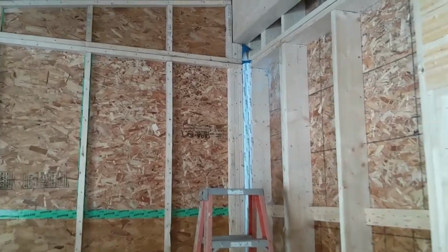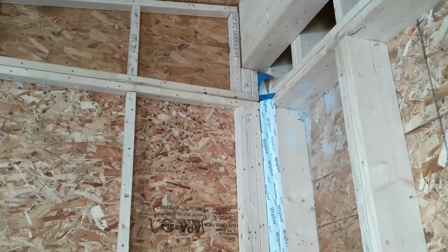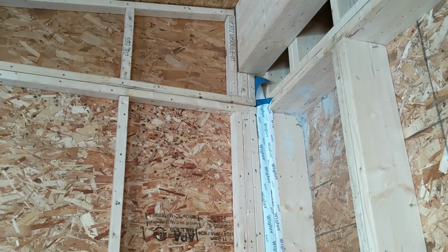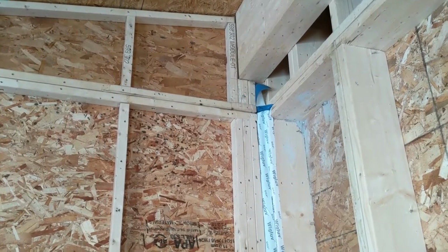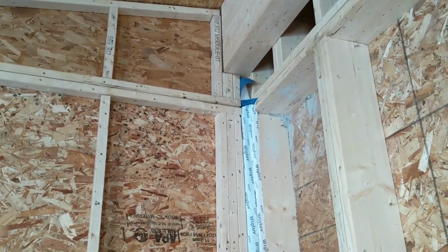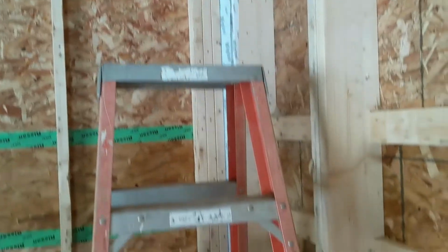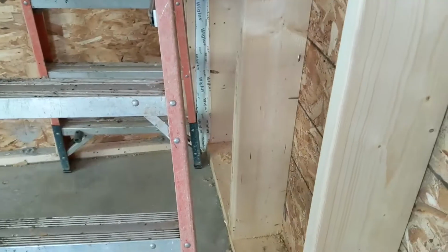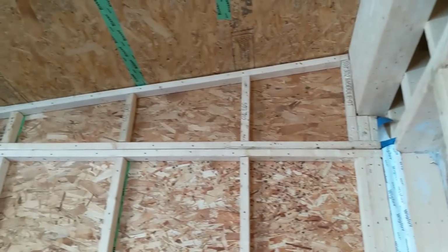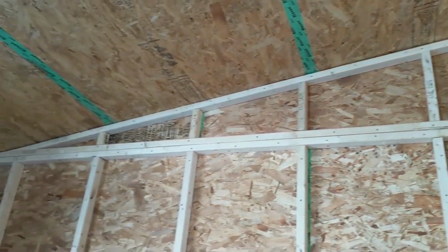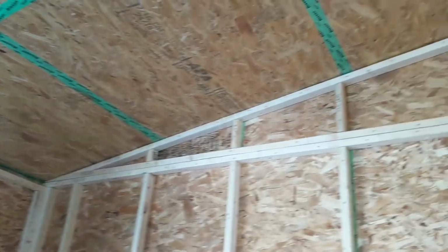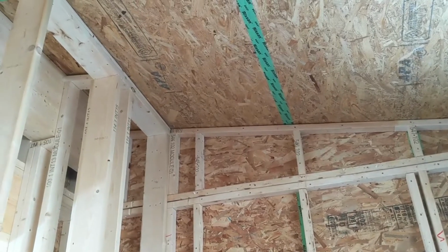This is another potentially tricky area for air sealing, at the roof and wall and timber of this office guest bump out. There's just a lot of stuff going on here, and I was up there on the ladder feeling for air leakage, fully expecting to feel some and to tape it up, but I didn't feel any. So kudos to the guys who put the shell up. Same thing with that joint between the roof and the wall panel. Occasionally we'll get some leakage there if the gasket's not perfect, but it's really good all the way around. So no need to do any reinforcing of the air sealing in these joints.